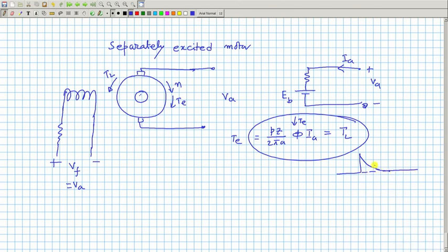If the machine is under absolutely no load, with no eddy current and frictional losses, then the final armature current will be 0 and it will run at a constant speed without drawing any current. That means Eb, as the speed was increasing, will become Va, so that no current is drawn.